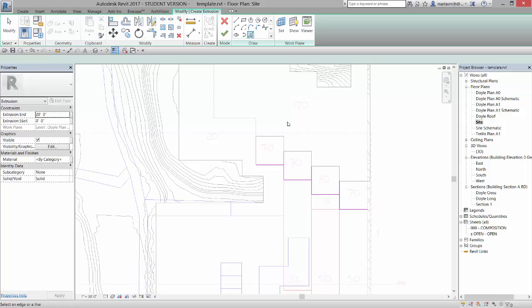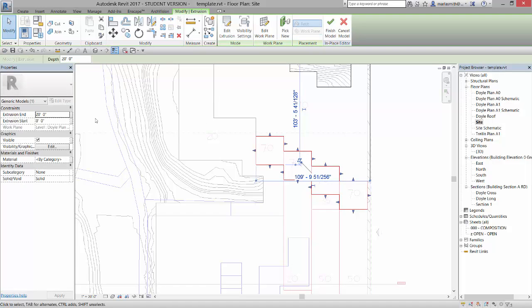And let's do a pick line here, here, here, here, and here, and we'll trim those out. And then all we need are lines here, here, and here, and then big green check, and those are going to need to be 85 feet if we add the additional amount.